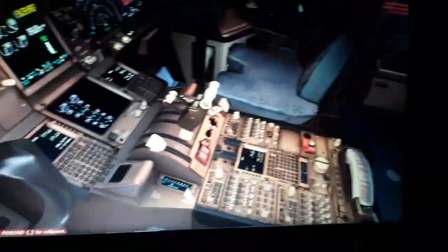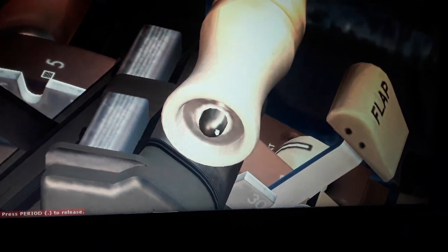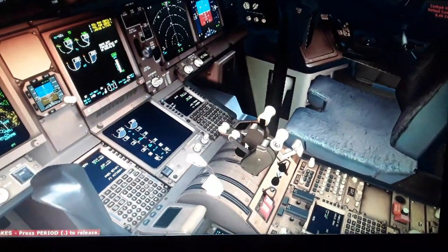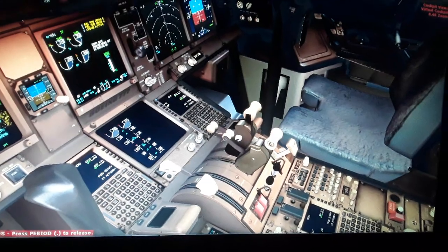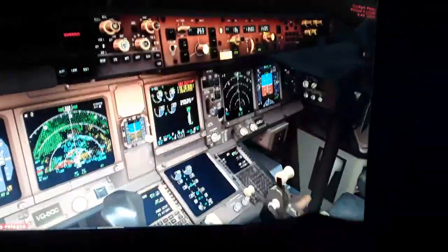So we have the engines, the left and the right. We have the auto throttle. Disconnect over here, you can disconnect the auto throttle. We have the takeoff, go-around, the thrust reverse. So you can move one engine at a time, forward or aft. If you have an engine failure, you will see it. It is also that, one engine at a time.